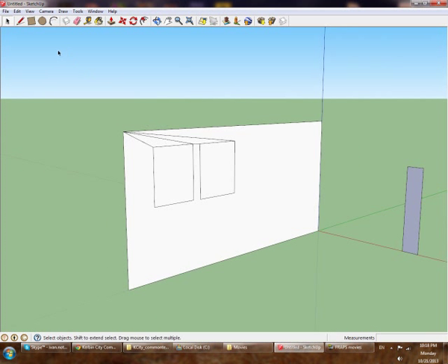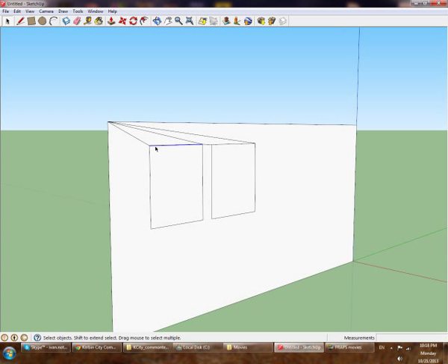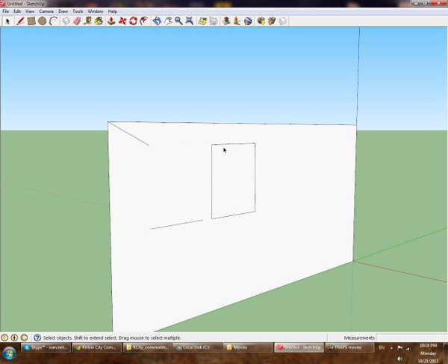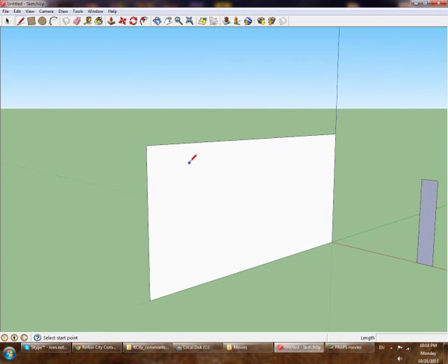What that means is just like I did it previously in 3ds Max, where I cut the whole poly when I was making the windows. And this is what you're going to do in SketchUp as well. So you're not going to cut a rectangle in the middle, but actually try to cut the whole side like this. And now we are sure that these 3 quads are going to be 6 triangles that are going to be divided like this or like this, right?